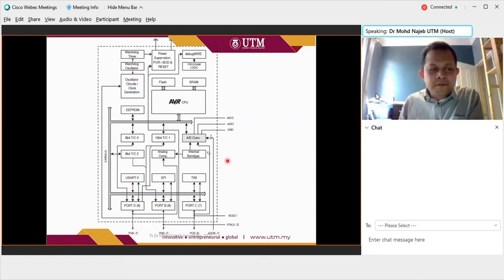Therefore if you do some programming like MATLAB, you can use your serial COM port library to read data from the virtual UART of the USB to serial connection.